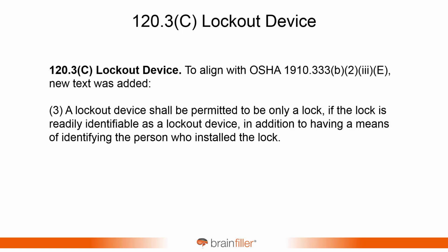The lockout tagout device. There was a change made here to align with OSHA. And that's something that happens from time to time as well. That NFPA 70E will have language, but then you start looking at OSHA, and OSHA will have language about the same item, and then you realize the language is a bit different. It's like, ooh, something has to give. Well, it's 70E that's going to give.